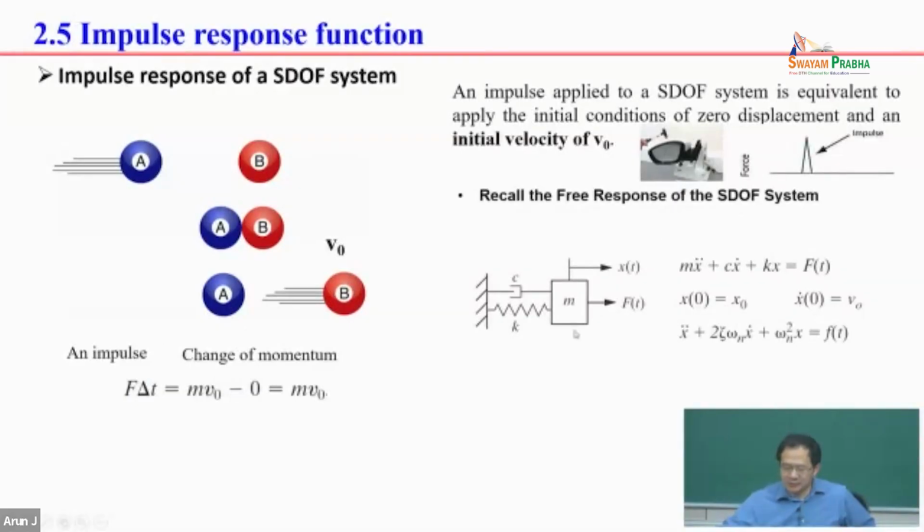If the system is at rest at the beginning, after you use the hammer to hit it, you get an initial velocity, x(0+). What I mean by 0+ is right after time becomes positive, you get a small velocity based on the impulse, the momentum change.